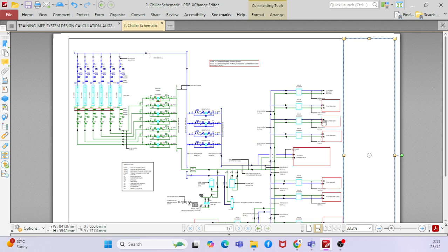To make it a circuit, you have a pumping system. The pump circulates the water from the chiller to the building, and then takes it back from the building to the chiller. That is what the pumping interface is doing. You have heard that there are two types of pumps: one is the building pump, and the other is the primary pump.